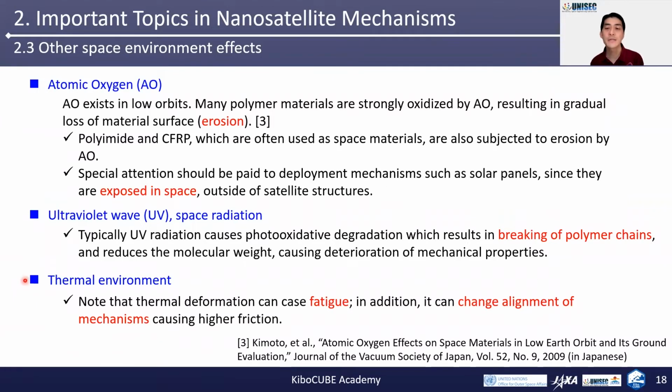And third, the thermal environment can be quite harsh in space. Please note that thermal deformation can cause fatigue. In addition, it can change the alignment of the mechanism, and it may cause the higher friction during the motion of the mechanism.